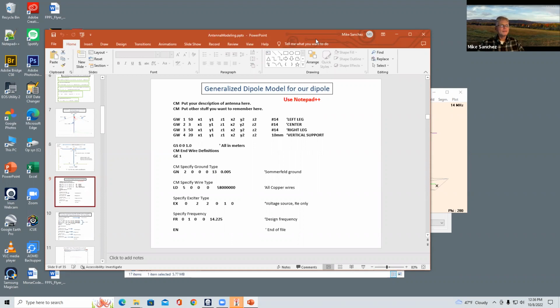So we did that. I've even built for someone a dual dipole. This was really cool. It's easy to do once you know how to do it. A dual orthogonal dipole like this that's perfectly omnidirectional. And you guys might know that in order to do that in real life, you have to do 90-degree phasing with a quarter-wave bit of coax, and then you'll get an omnidirectional result from two crossed half-wave dipoles.